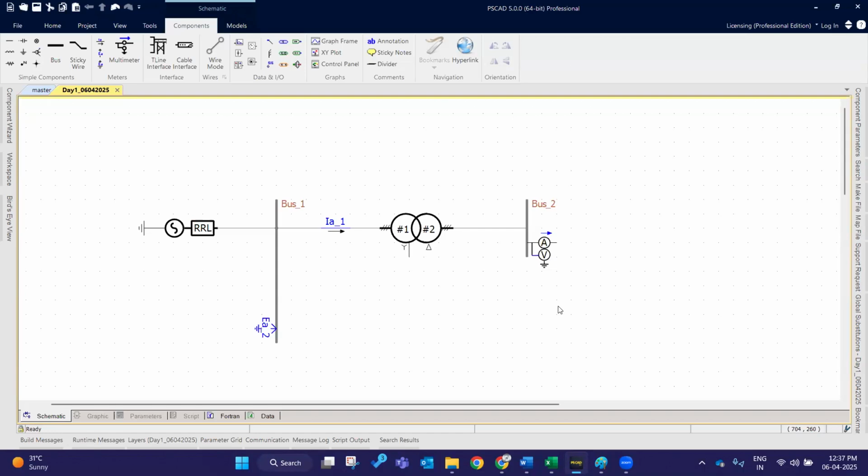So hope you understand, right? For example, why I'm insisting on ETAP is that ETAP is actually a basic tool. If anyone is starting with power system studies, if he starts with ETAP, it will be easier to understand all the other softwares also, right? So in ETAP, if you run the simulation, nearer to the bus itself the voltage loading will appear. It will be showing the real power and reactive power flow. If you want it in terms of power factor and current, that also will appear.